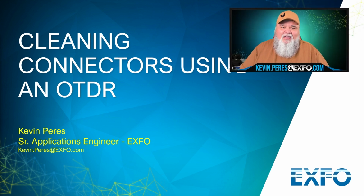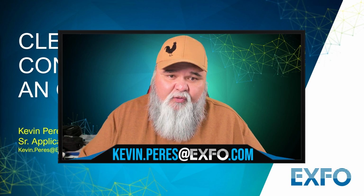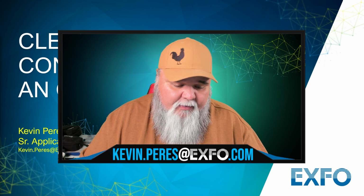And so, obviously that sounds kind of funny, but really what it is, and I've talked about this in some of my longer seminars, so I really wanted to create a shorter video on this. When I was a technician and I worked in an operations center, one of the biggest issues that we had was dribbling errors. So these are errors that slowly dribble in, bit errors, into your system. And more often than not, it was a dirty connector, probably 80+% of the time.